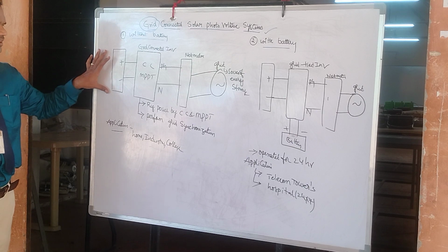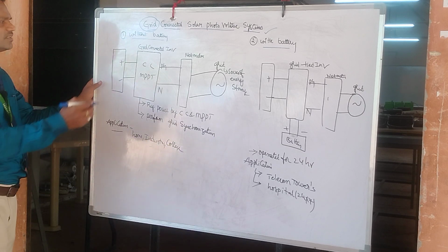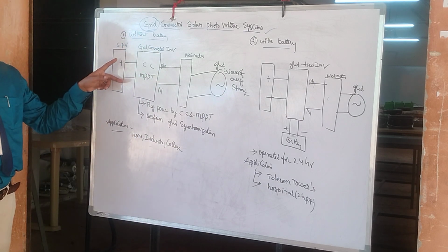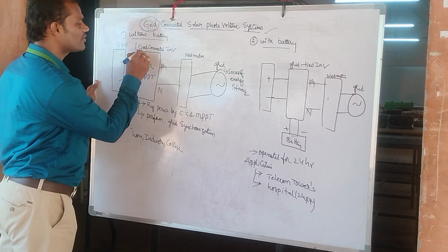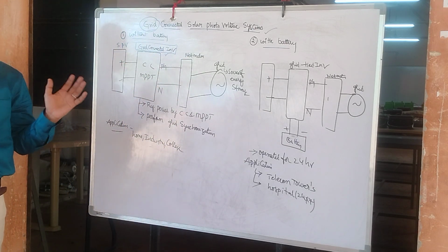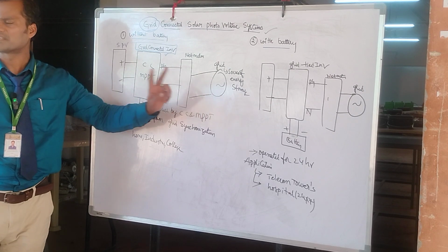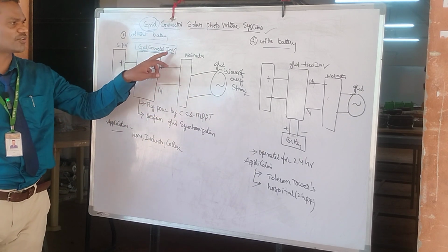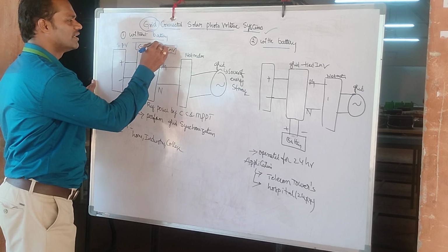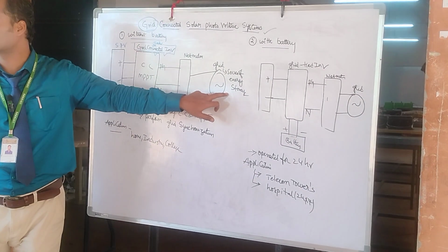Already we know that we have to connect a number of solar panels in series or parallel connection as per the voltage requirement, which constitutes the solar PV system. The output of a solar PV is nothing but a positive terminal and a negative terminal. We connect it to an electronic control unit, which is now called a grid connected inverter, but the components are the same. Only the name is changing. Why? Because it is called an inverter when the input is DC and the output we require is AC. It performs DC to AC conversion, so it is called an inverter. This inverter is also called a grid tied inverter, because it is tied to or connected to the grid. That's what is called a grid connected inverter.